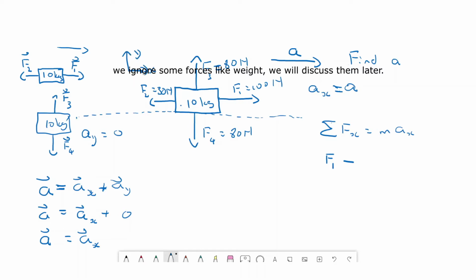That's what I always do. All right. So according to this convention reference frame, since F2 is facing towards the left, the arrow is pointing to the left, I have to take it as negative. Then that is going to be F2. Now I am told that the object is going to move to the right, which is positive, so it's just going to be MAX.